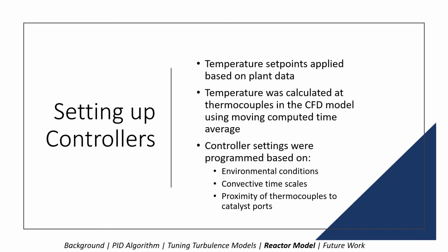This study involved implementing data from actual reactors to be used as a set point for each controller. Within the CFD model, thermocouples were modeled to replicate the actual reactor. So each thermocouple would be located within the CFD model where they're actually located in the reactor. Temperature data from the controllers was taken at each thermocouple geometry, and the data was sent to the controller after